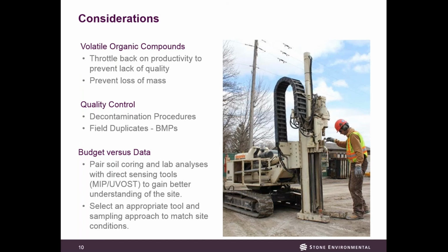So having a good dialogue between your geologist and your driller, and saying, we're not here to make 200 feet of coring today. We're here to do this in a quality manner. So having no more cores coming at you than what you can actually log. Obviously you don't want to be waiting for the driller to bring you a core, but a good driller will be looking at you and knowing that you're ready for another core, and having constant communication so the next core's coming in and you're right there for it.